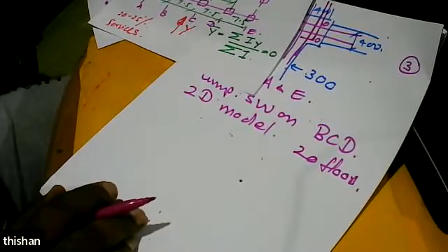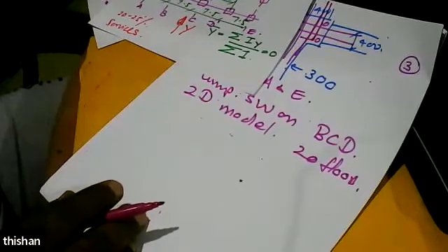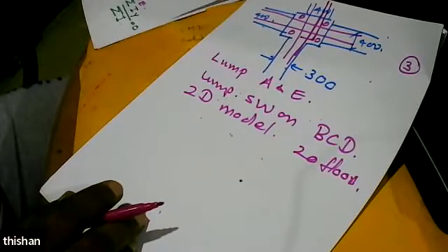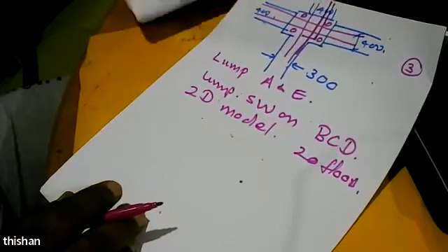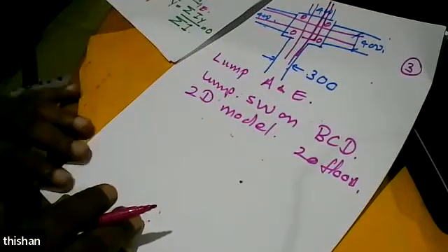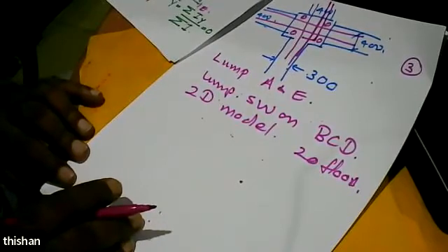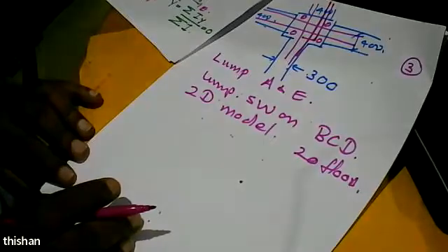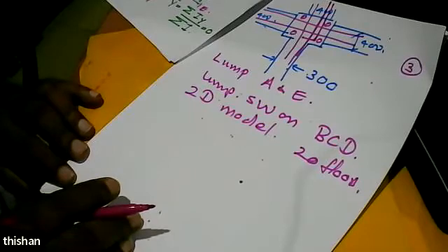And we know it's having more than 10 floors, that means the lateral deformation behavior is important, because part of the load will be carried by the shear walls, part of the loads will be carried by the frame. In the lower floors, the shear wall will carry almost all the lateral forces, whereas in the top part of the building, the walls will become more flexible, and because of that, you'll find the frames also can carry significant lateral load.